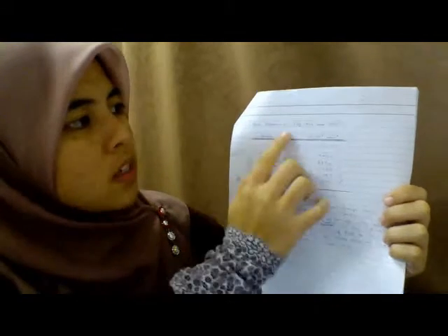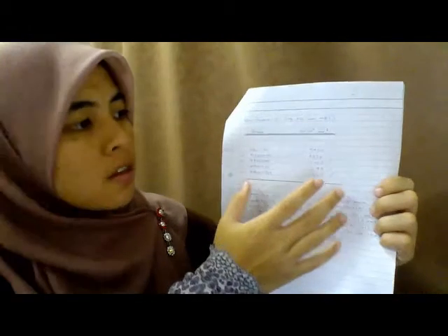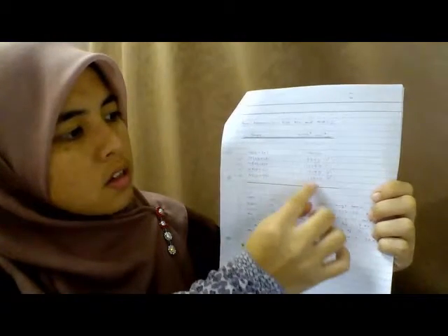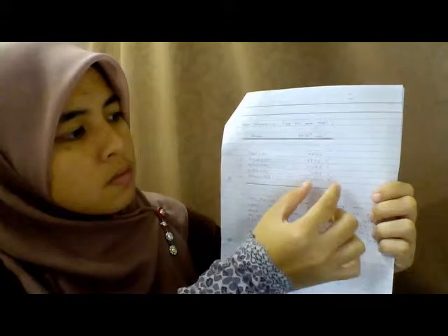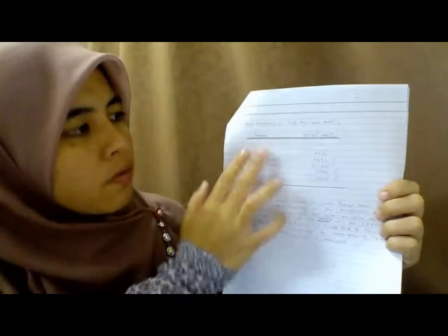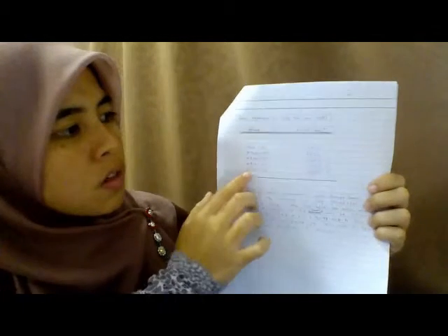To find the wide flange beam, we can get it from the appendices, which is at page A14 and A15. So we list all the values where S is larger than S min, and I have listed about 1, 2, 3, 4, 5 shapes that are suitable because the value of S here is larger than S min.